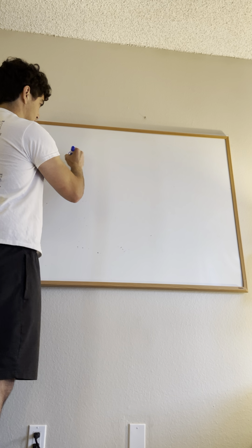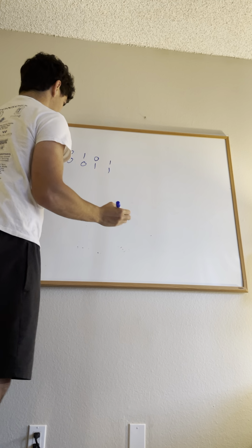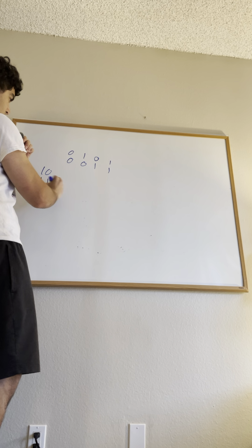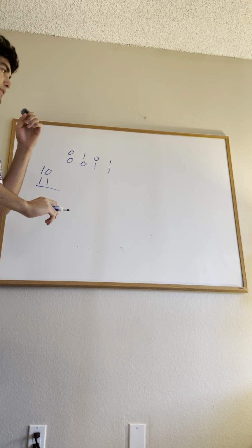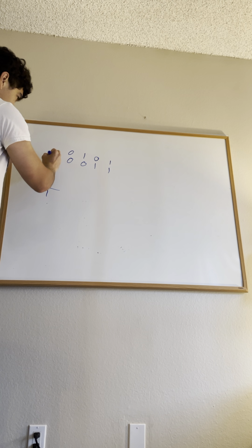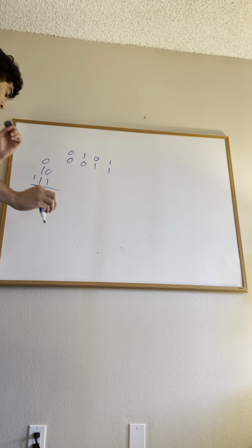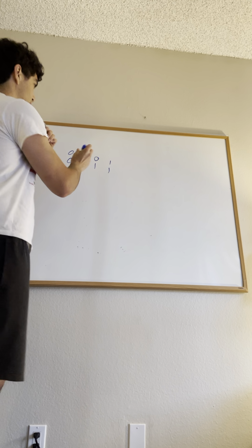So, we only have these possible cases. And remember that when we do something like this, we have to do two things. We sum the bits, and then we see if we have to carry over. So here the sum is going to be 1, your carry is going to be 0. Here your sum is going to be 0, your carry is going to be 1 over here. So our circuit needs to do two things. It needs to output a sum and output a carry.